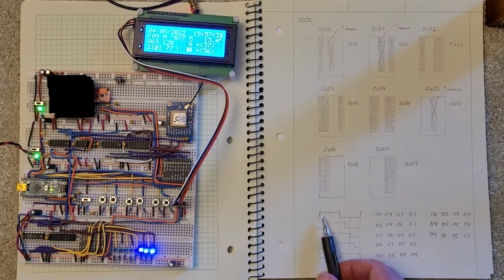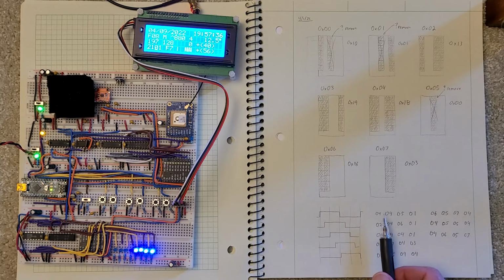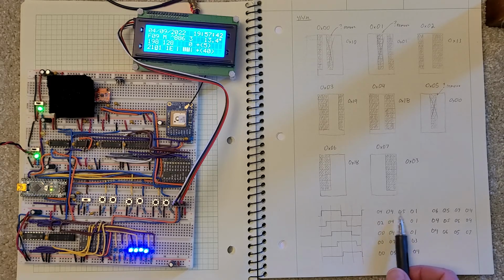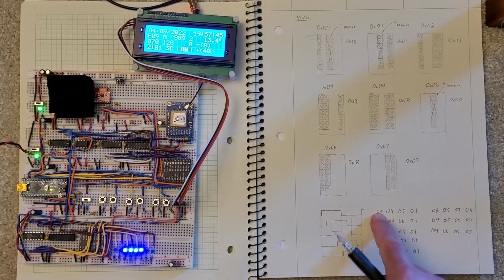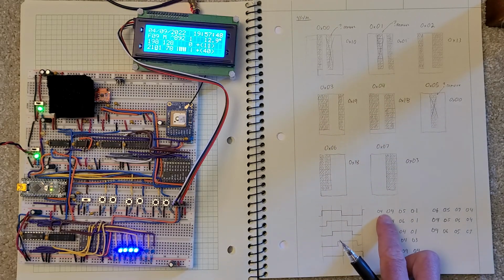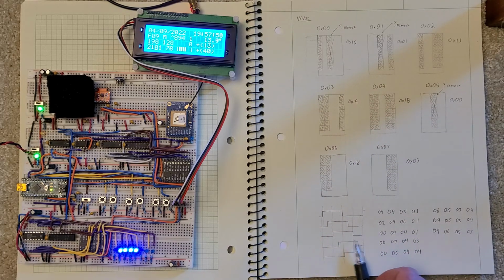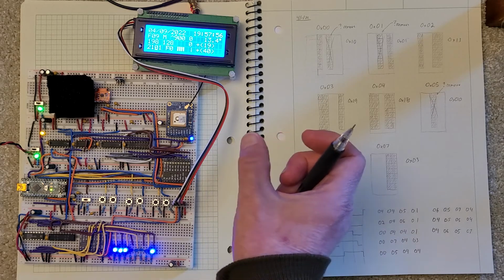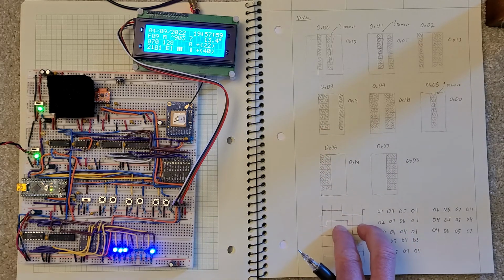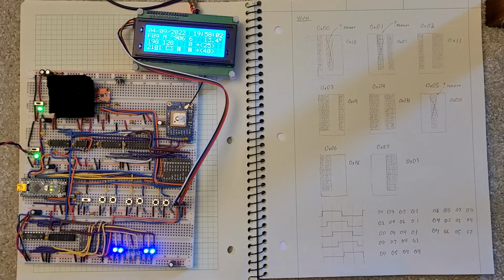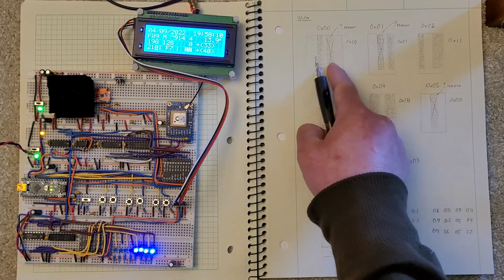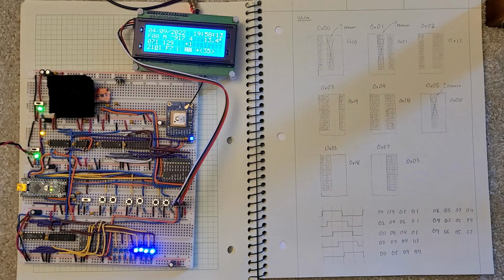So for each of the clock edge positions, I did a test where I drew out what characters, so 04 is the character which corresponds to this. And so for each of these 8 clock positions, I drew out what the character is going to be. And so I made a program that every second just walked this clock edge pattern along. And that's how I verified that I like the way the display works. I was able to tweak it by getting rid of these reference blank marks.